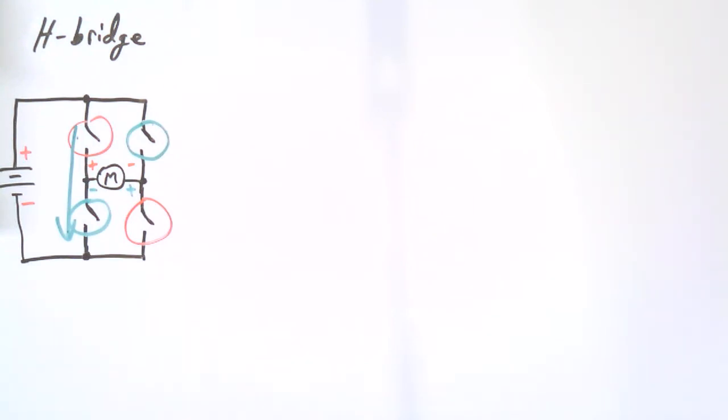In fact, some H-bridges designed with transistors, they'll have to work around that. There has to be an off time to allow the transistor that's turning off to turn off. So to switch, you don't necessarily turn one off and one on at the exact same moment. They'll both be off for a split second, and then the other one turns on. So to avoid shoot through.